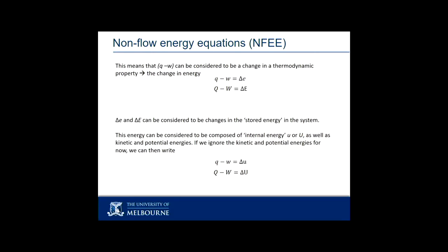If you were to start solving a problem, say, identify that this problem is a non-flow problem and I am going to apply the first law non-flow energy equation, you could begin by writing that down and you're good to go. Again, because I've made so many mistakes over my life, I'm in the habit of writing down the first law as E in minus E out equals delta E, and now I'm going to cancel these terms so that when you read my work, you can see exactly what I was thinking.